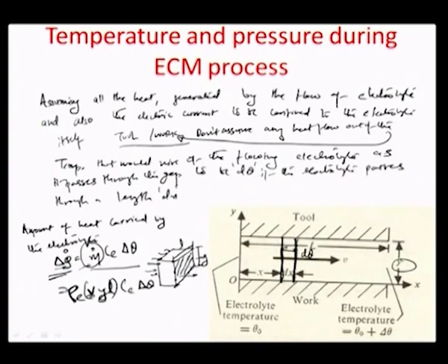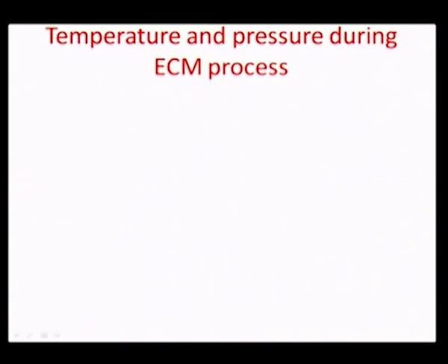So, now we would somehow like to find out a relationship between the current density, which is the main reason for the heat transfer from the tool or the workpiece onto the electrolyte. Okay. And if we look at that, the electrical power due to the current density, which is dependent on the flow of the ions, right,